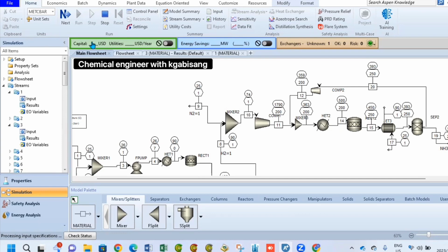At high temperatures and pressures still, a second heat exchanger is used just to slightly increase the temperature from 300 to 500. Now, this was determined to be favorable for our Haber-Bosch process, whereby we react nitrogen and hydrogen together to form ammonia. The reaction takes place inside of our second reactor here.